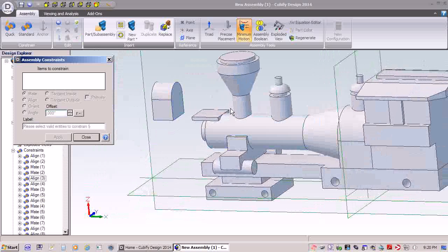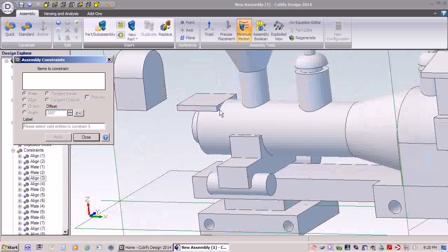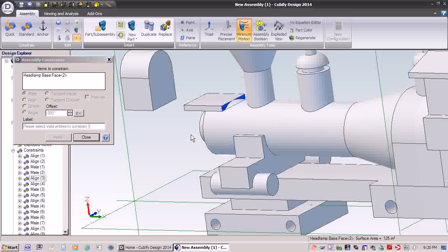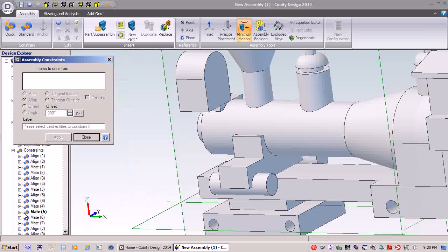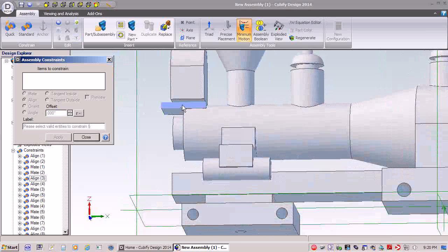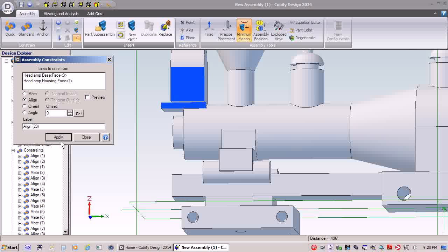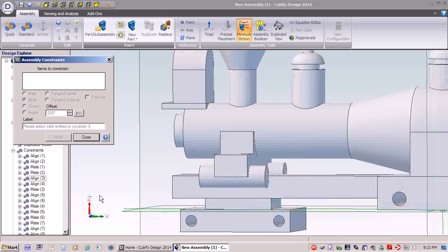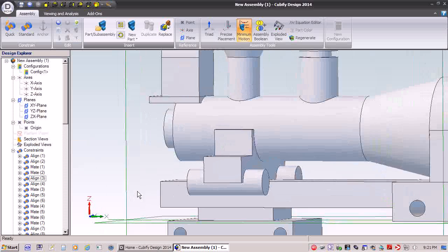These happen to be the same dimension. So this is a small little face to try to get here, but that's going to be a line. They're going to be right up against each other. And line it this way. Again, this one is also flush. So we did the mate and two lines, so he's locked in.